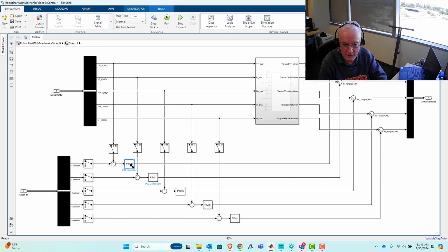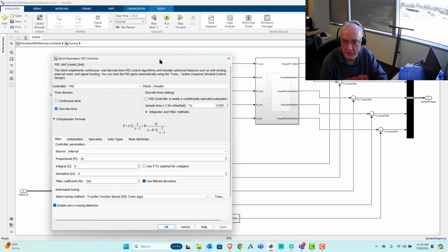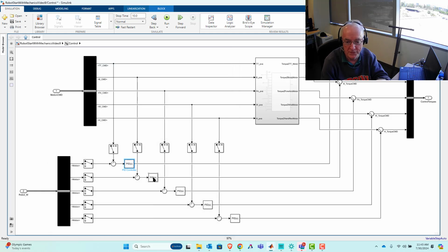And so again, you'll recall, and I made a point when we got into this, that this doesn't happen without a good feed-forward controller, right? But that we were somewhat loose and maybe a little bit arbitrary in just choosing a value of 10 for the proportional gain, 0 for everything else, and that we got it to work with that too, right? And again, it's because we had a good feed-forward controller, right? So let's just continue on that path. We'll just copy this in for each of them.